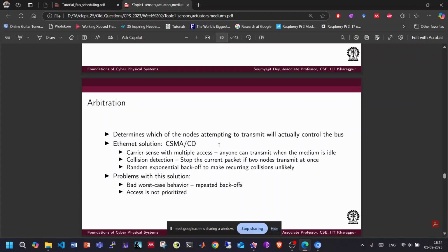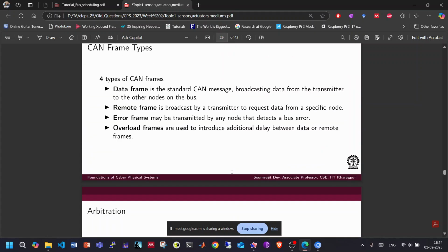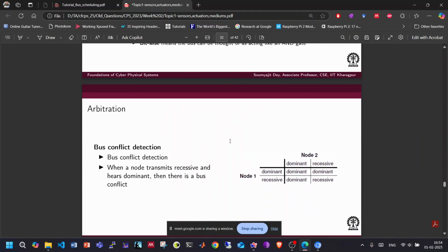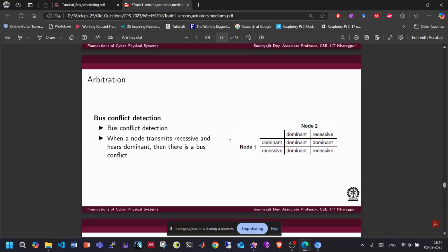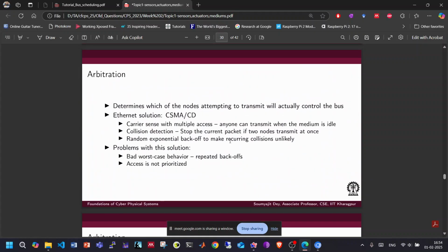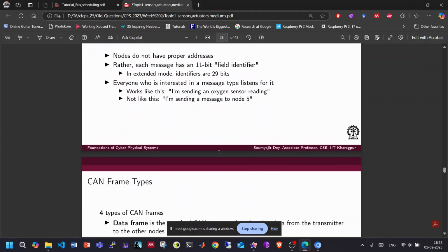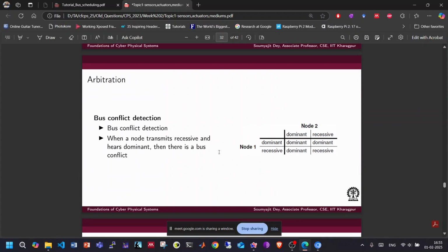So there are obviously other protocols, but in CAN, how arbitration works, I told that already briefly while I was discussing that when someone has a very low ID, their data is transmitted. That is called arbitration in the CAN bus. And for arbitration, we only use the ID field. We don't use the data field for arbitration. Arbitration is something we use to decide which data should be transmitted, and the one having the lower ID wins the arbitration. By winning the arbitration, it is allowed to send the data. Make sense?